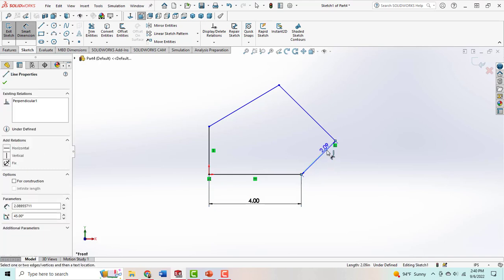Please notice that when you are dealing with a slanted edge, you need to bring your dimension straight out so that it remains parallel with that line you've selected. Because you can see here, if I just have the dimension how it is right now, it's showing me that this line segment's true length, since I am parallel with the line, is 2.09. Now if I were to bring it down straight, you can now see that dimension has changed substantially to 1.48.